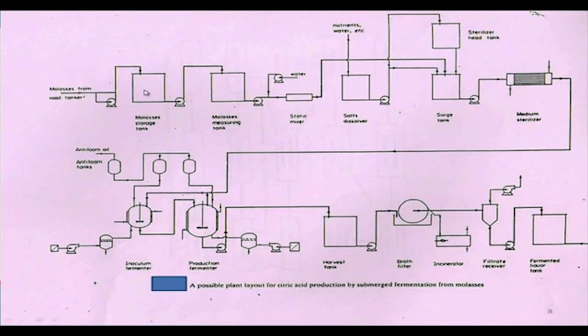But we observed we have acute scarcity. Off season we have the acute scarcity of cane molasses, because in India cane molasses is also used largely for ethanol production. So we replace the cane molasses by using the hydrol. Hydrol is a byproduct of the glucose industry: after crystallization of glucose, the mother liquor contains about 50% of sugar, that is replaced by the molasses. So we successfully replace a portion of the cane molasses during the off season,